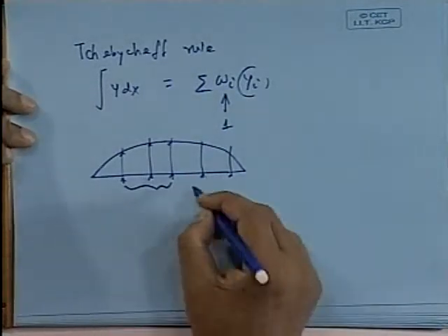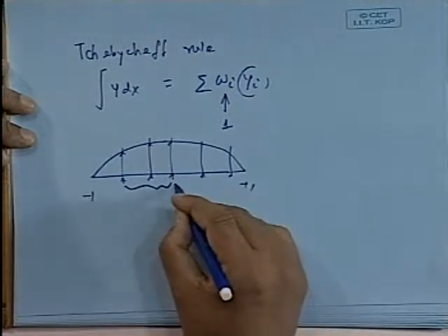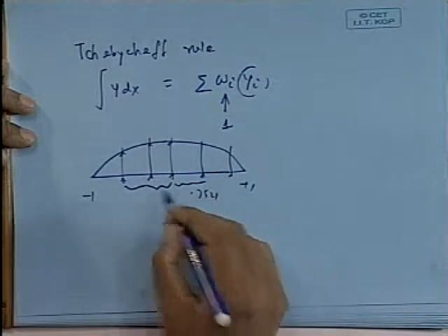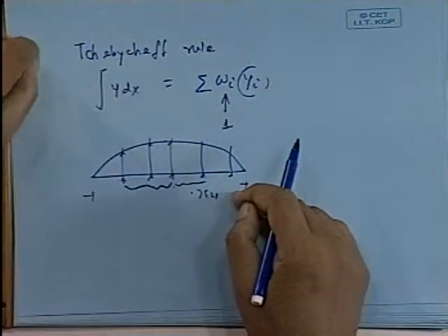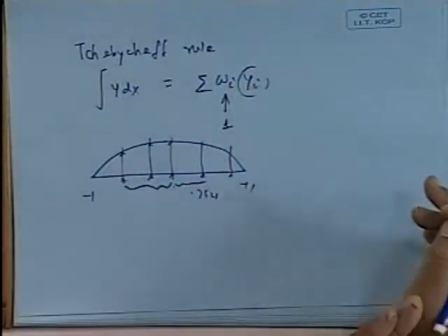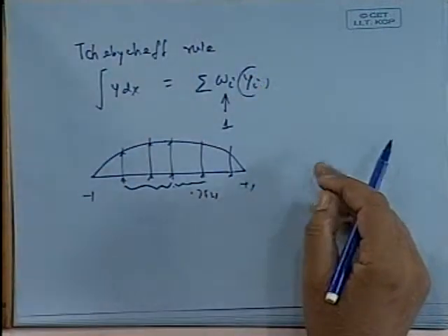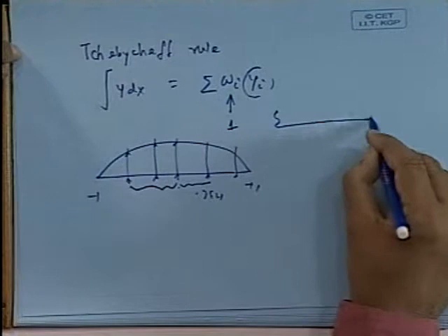Now, for example, suppose this is -1 to +1, so this distance might become 0.7821, some odd number. It has been found that if you take the station spacing at that location and just add them up, you get the volume. So they are not conforming to the standard ship stations.